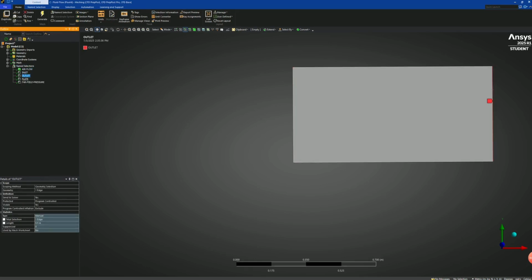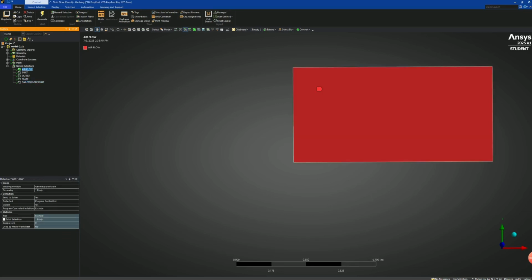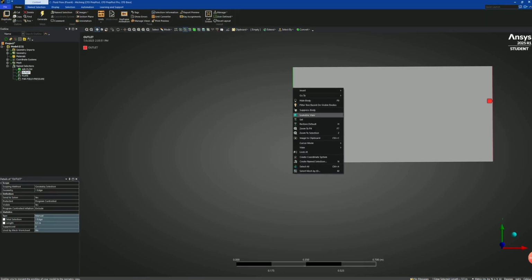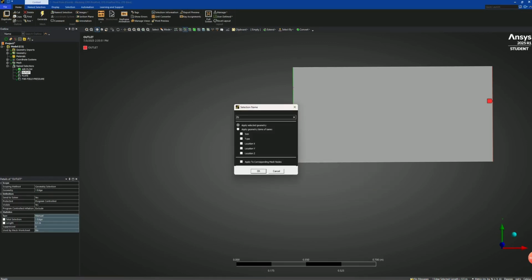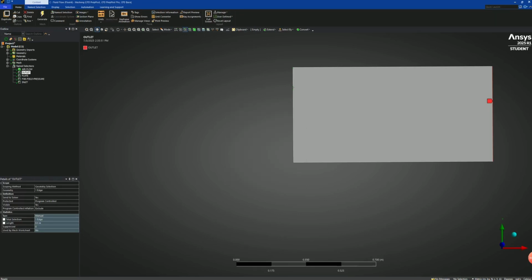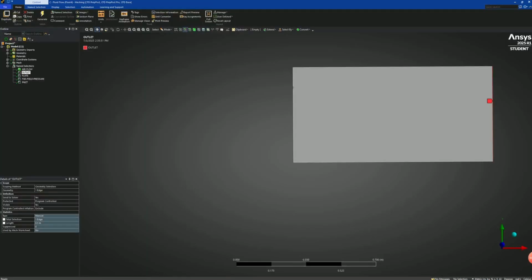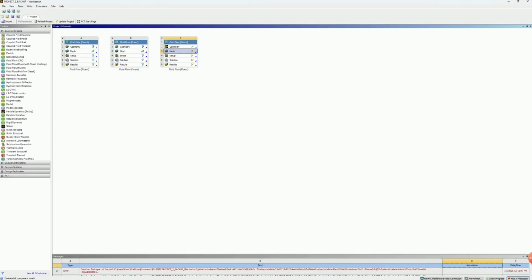Then what we want to do is name our surfaces, our selections. We're going to start with creating a named surface, Airflow. Left click using the face selector, and then right click to create a named selection. And then use the edge selector for that, such as seen here. Create manual selection. So we click on that with the edge selector, we right click, create named selection, and we get that. Make sure we save as we're going along. If the program crashes right now, it'd be pretty devastating for the entire experiment.